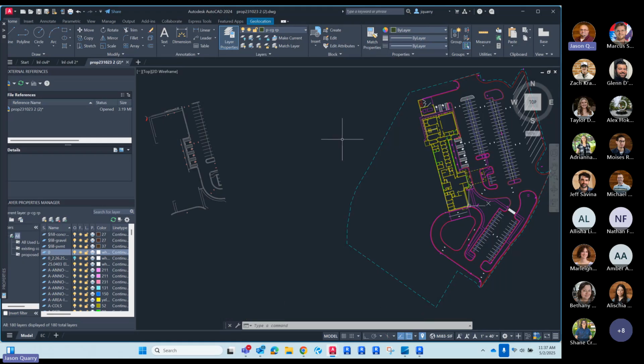The one thing I will say is if you've already linked it and you realize that you're having this issue, and you go create a new version and you double click it, you open it up, you do the edits, you move it closer to UCS, you save it over top of the original, I still suggest removing it completely from the Revit model and relinking it, because it doesn't always automatically fix itself. It's already been linked too far away from the 0,0 base point, and it's probably going to stay jagged the entire time. So you're better off just to remove it from manage links completely, then relink it, and then you should get cleaner line work.